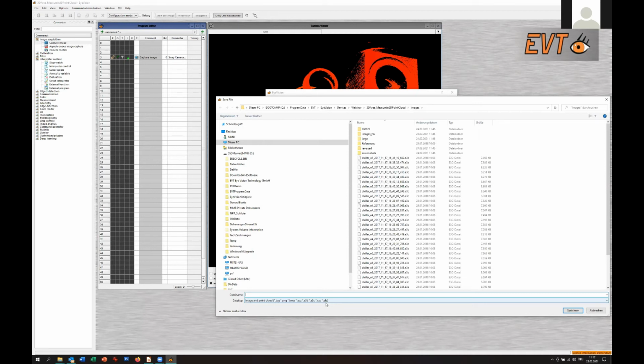point cloud. If you compare the size, I highly recommend to use the E3C. This is a compressed file format, lossless. We don't lose anything. So if you store the point cloud, it's exactly the same you got from the sensor. But if you compare these E3C point clouds with either the uncompressed or even with the PLY, which is also uncompressed, you will see they are on average 10 times bigger.